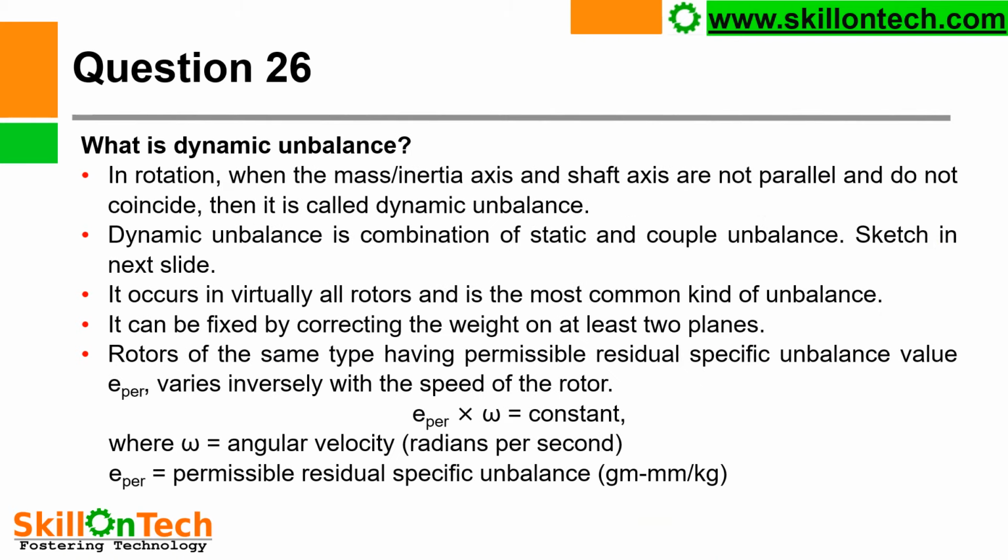What is dynamic unbalance? In rotation, when the mass inertia axis and shaft axis are not parallel and do not coincide, as we discussed earlier, then it is called dynamic unbalance. Dynamic unbalance is a combination of static and couple unbalance. The sketch of this dynamic unbalance is shown in the next slide. That will clear your understanding.